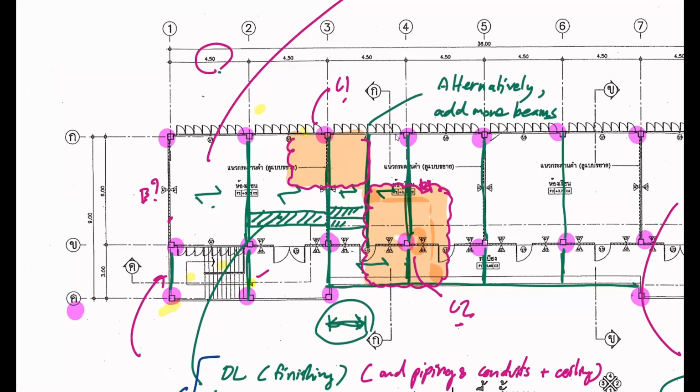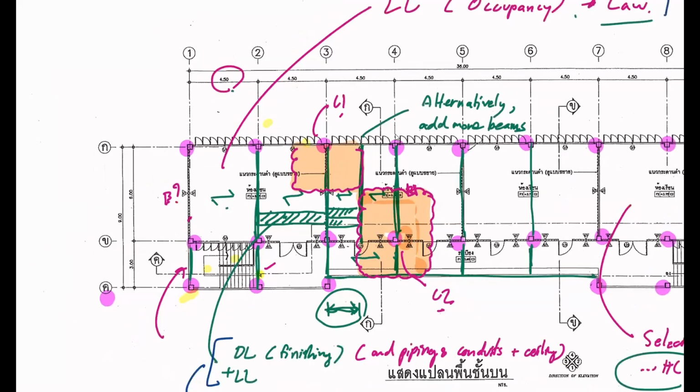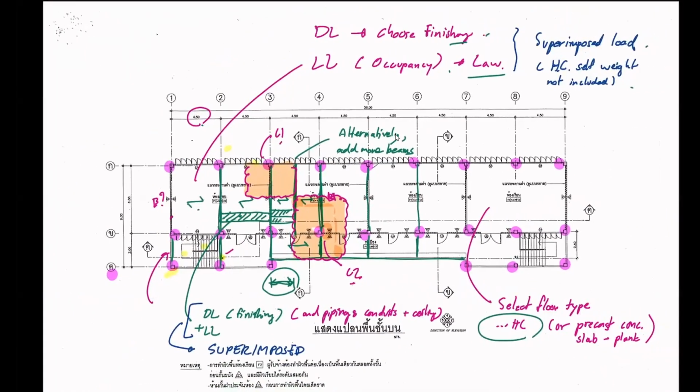So you end up with this beam is going to be quite heavy because of a wall, you must know this as well. Maybe you know it from RC, but that's fine. Wall. We have half brick wall and a full brick wall. Half brick wall, it means that actually they use 1 brick for the thickness.